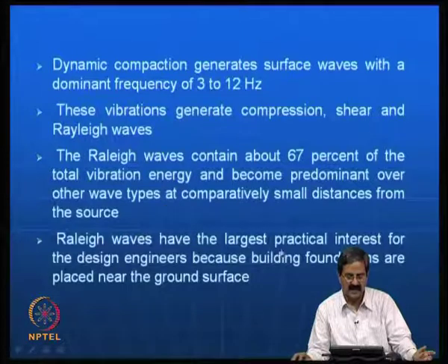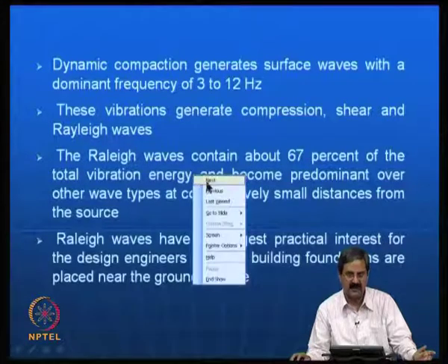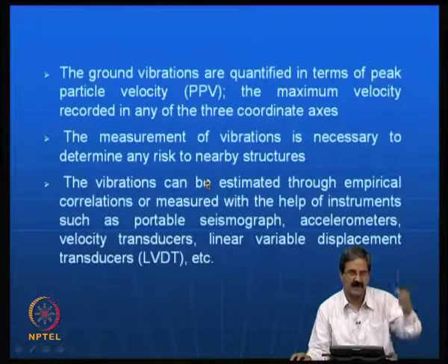So, Rayleigh waves have the largest practical interest for design engineers because building foundations are placed near the ground surface. Particularly, the Rayleigh waves should not hit the foundations that are next to the source. Here, the source means compaction.